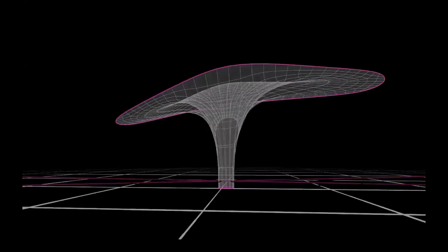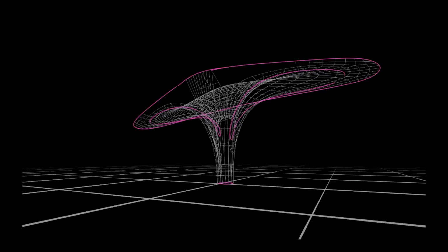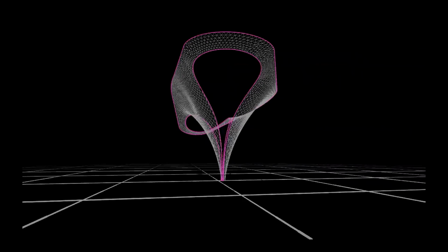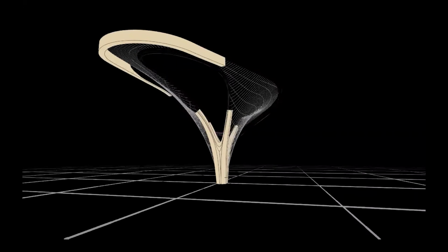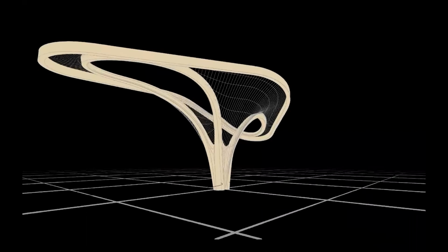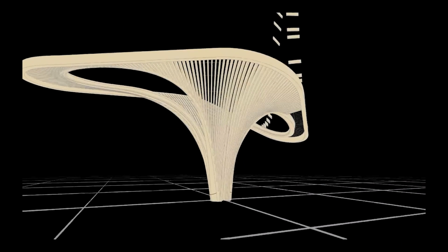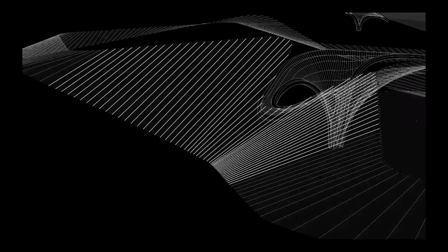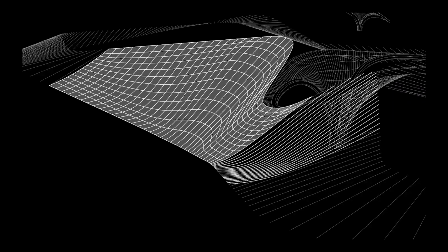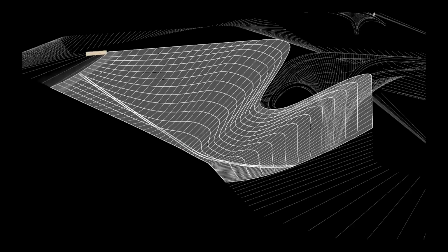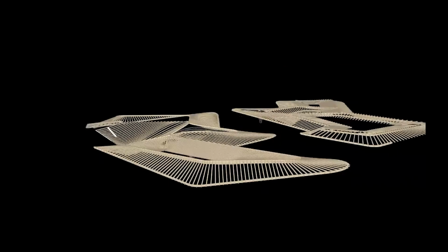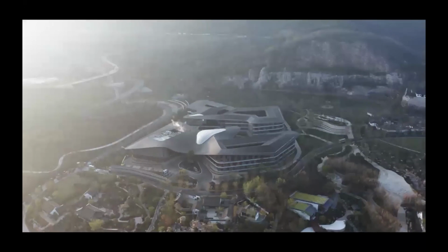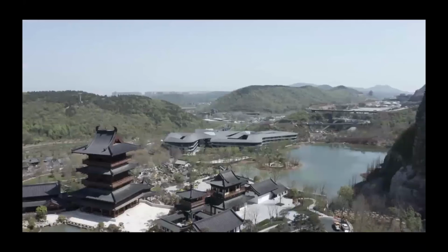To generate it not only by structure performance, but also by inviting light, introducing natural light into the lobby. And the mechanical analysis will help us generate this kind of performance-based timber support structure system and integrate it with the roof system. And for the cable hanging, because it's a super big span, like 30 meters with no column, we hang the timber structure on top of it by cable. So this is the project after construction finished recently.